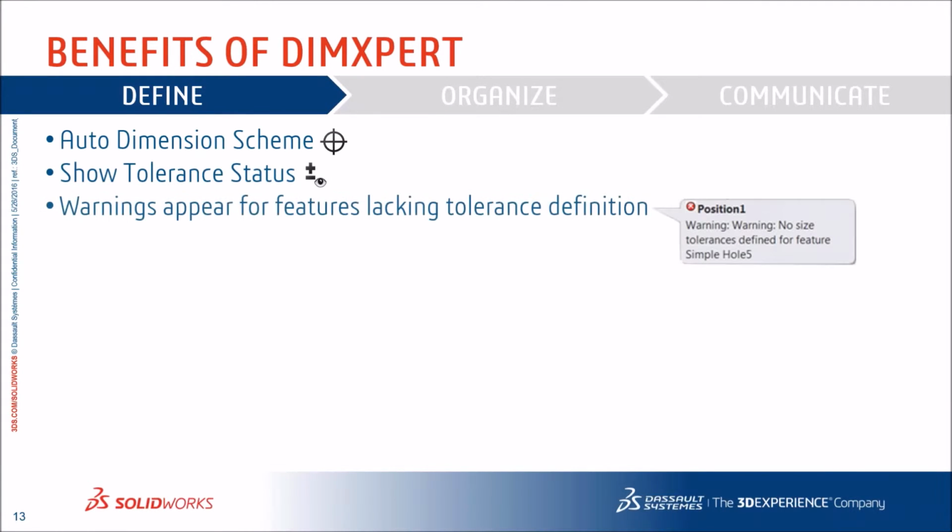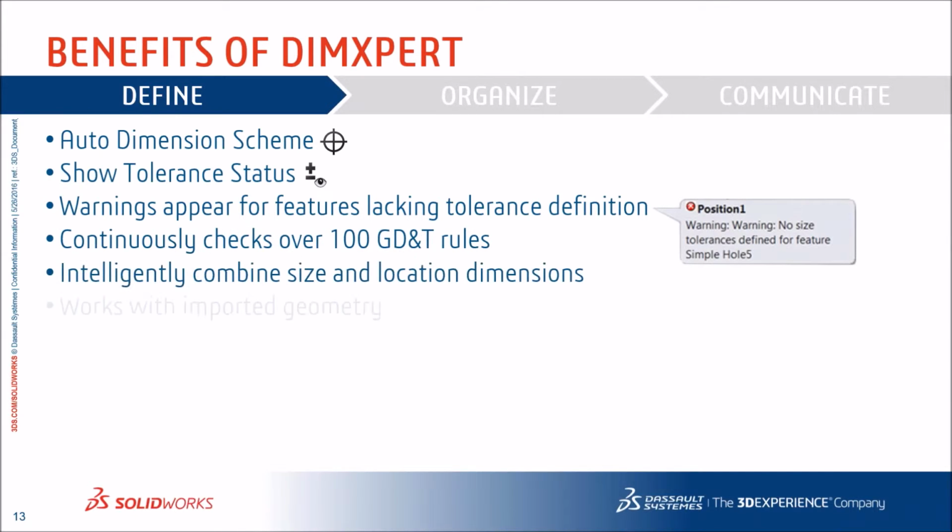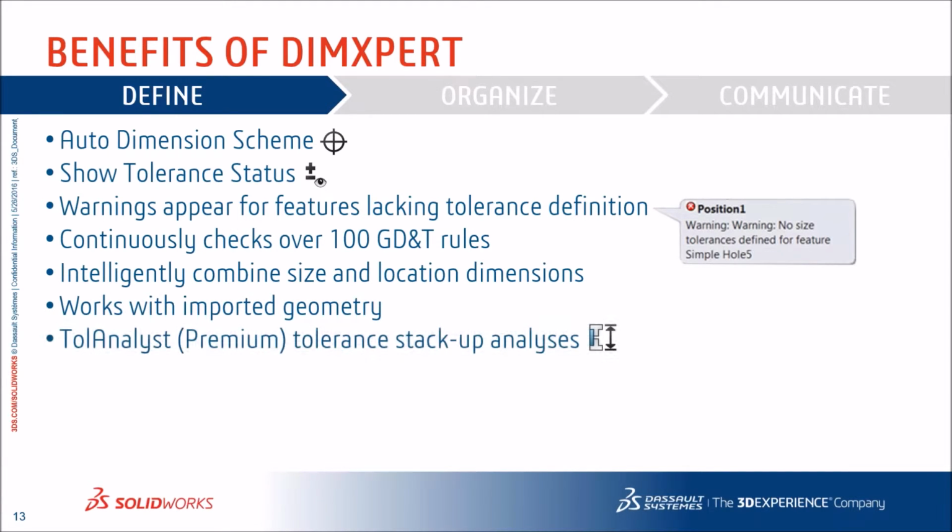So some of the benefits of DimExpert include an auto-dimensioning scheme, which again, you could set up per your document template, default tolerancing schemes, and dimensioning methods. And it will go through and define the features that you have pre-selected automatically. We can also enable the Show Tolerance Status Preview button.